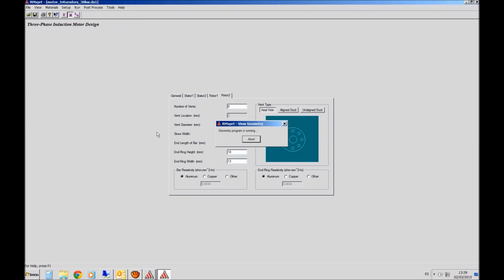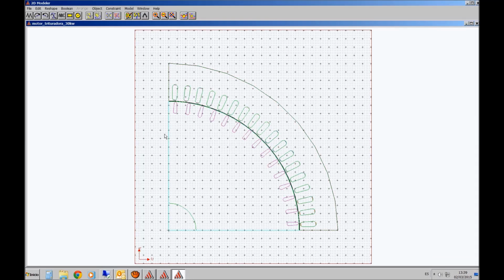This takes a little bit more time because, as you can see, it is a CAD design of a quarter section, because it is supposed your machine is going to be symmetrical. But anyway, I don't recommend you to use these quarter sections because boundary conditions are quite difficult to use.